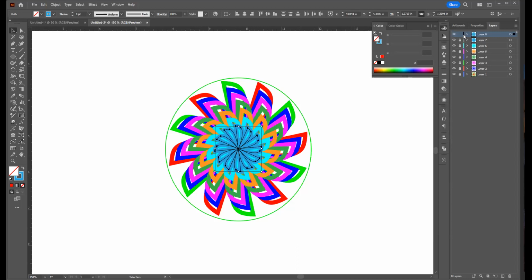So if you're ever wondering why your lines change color, that's the reason why: it's giving you a color right there that it assigns to each layer as you create them. So you can choose to use that color, just keep them together, or if you're using the same colors throughout, then when you select them, you can know which layer they're on easily when you come back over here.